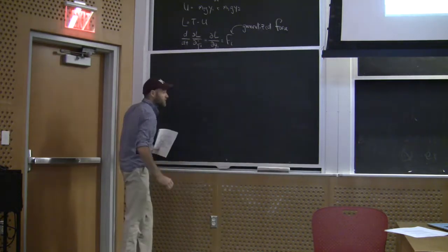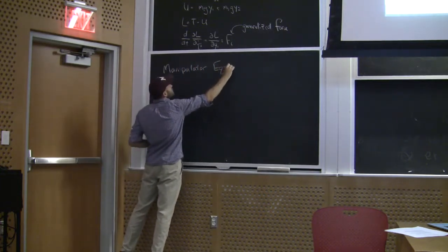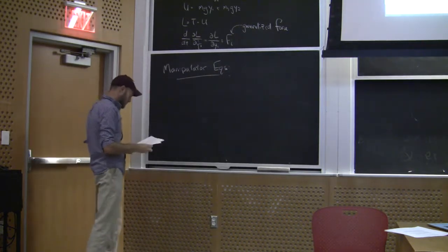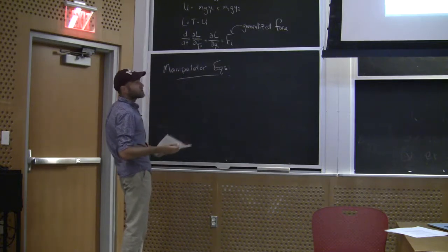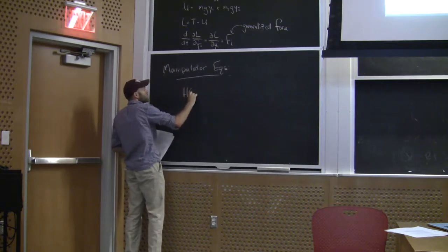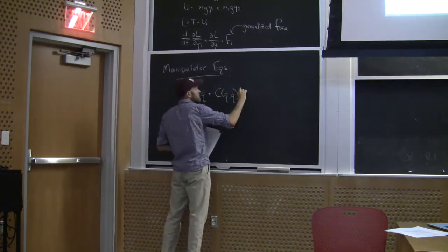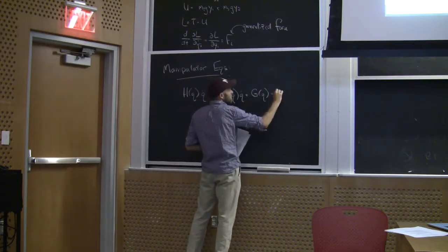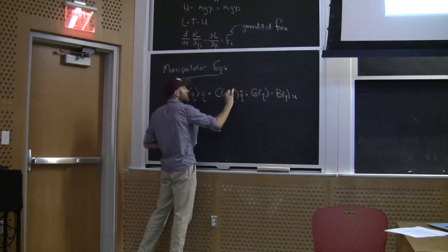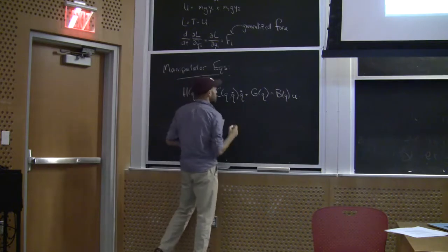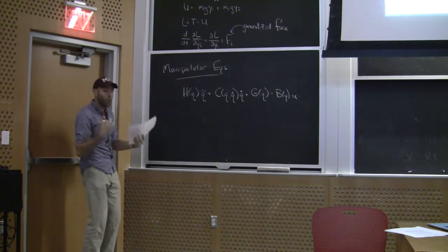They all subscribe to the famous manipulator equations. So it turns out that if I go through this process for my robot, whether it's the cheetah robot or a double pendulum, I'll come out with something that takes this special form. Sorry that the board's kind of marked up, so you have to make sure you can see all those dots. This is almost basically another way to write down my little f, but it's even got more important structure.